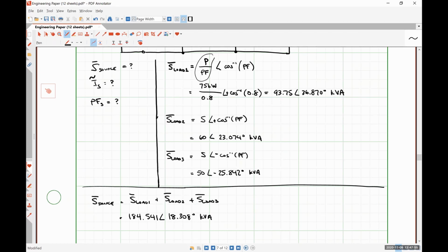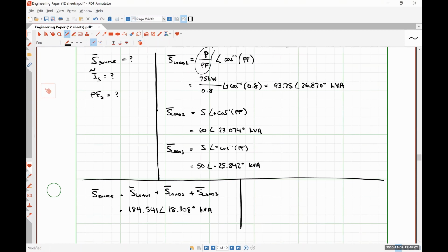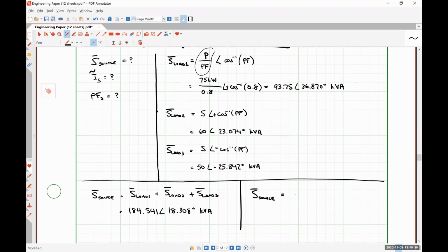Does anybody have any disagreement that the complex power supplied by our source would simply be the voltage supplied by our source multiplied by the complex conjugate of the current flowing into the negative polarity terminal, because we want to supply power here specifically, right?